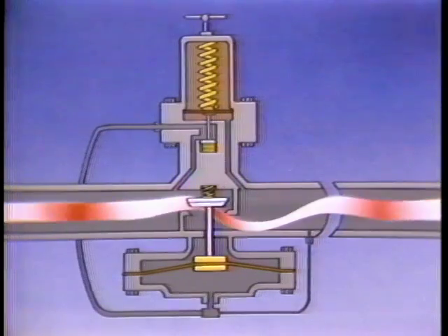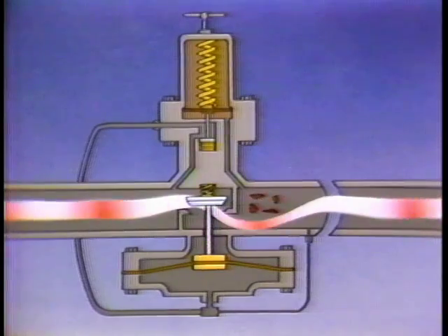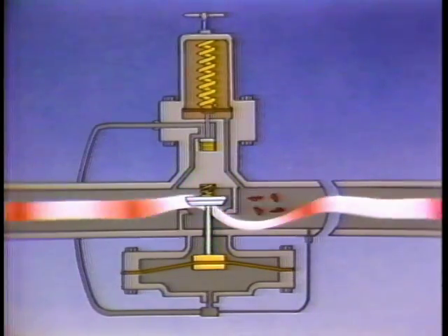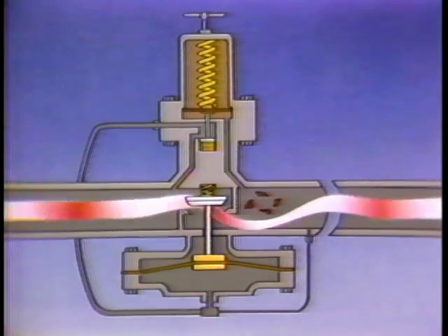With the large diaphragm to sense outlet pressure variations, turbulence at the outlet of the valve can cause instability, valve chatter, and excessive wear at low flows when the valve must work close to the seat. This limits flow rangeability.